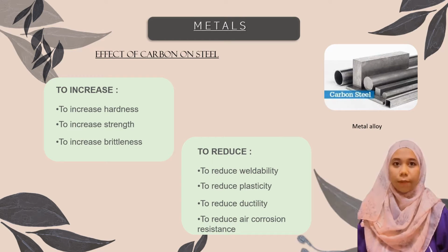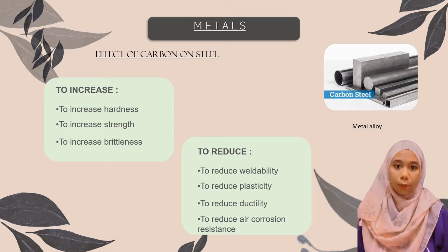So there are several effects of carbon on steel. The first one is it could help increase hardness, increase strength, and increase brittleness. But it could also reduce weldability, reduce plasticity, reduce ductility, and reduce corrosion resistance.